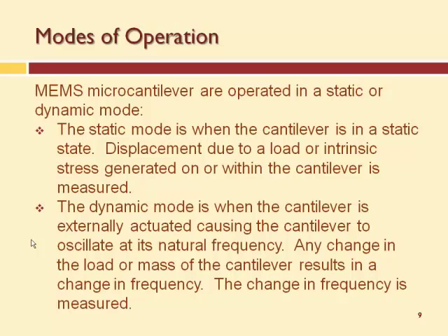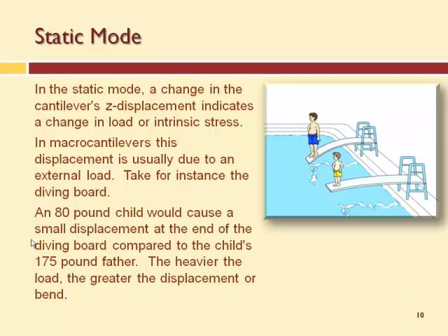Static would be the cantilever isn't moving, it just bends. It responds to some stimulus by bending, and you can detect the bending in multiple ways. So you've got static and you've got dynamic, and we use both modes of operation with microcantilevers.